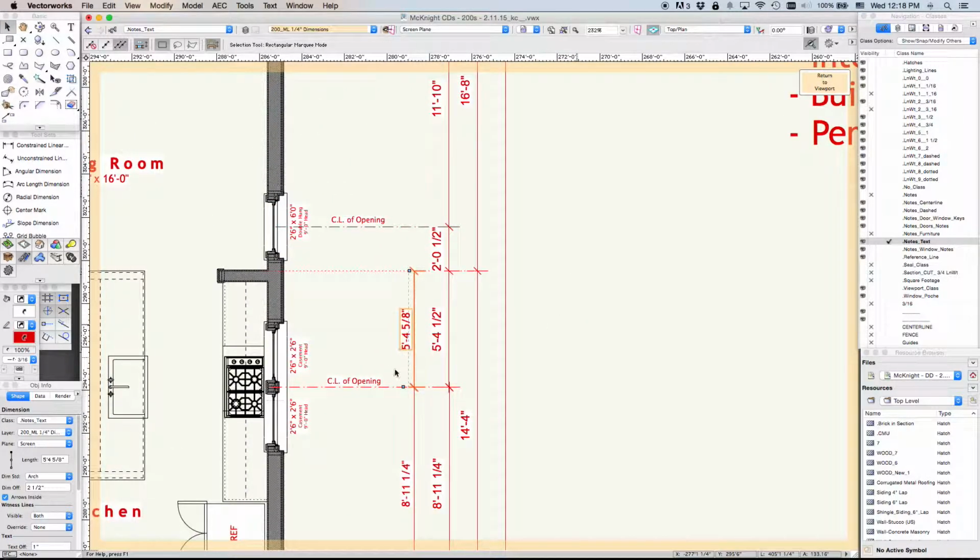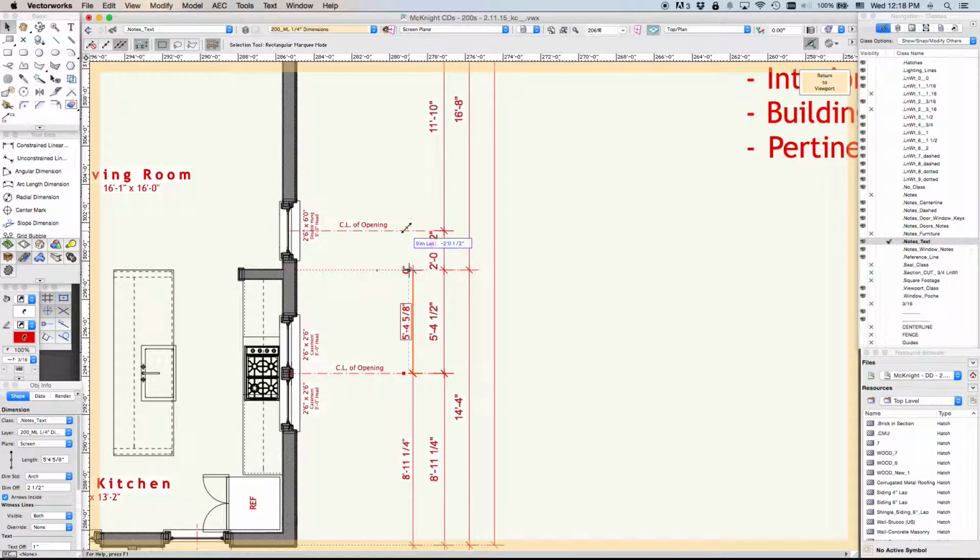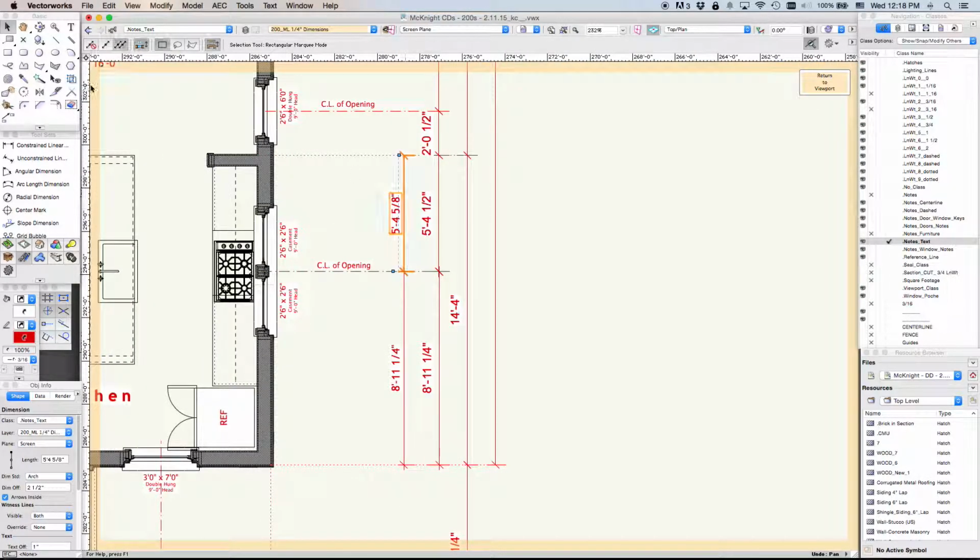You can just go down the line, duplicate, drag, duplicate, drag, and so on and so forth, and you can go through them pretty quickly. There's several different ways you do it. You could select it, do M for mirror, and then use it about this line. You can mirror it, and then just adjust the end, bring it back to that point.